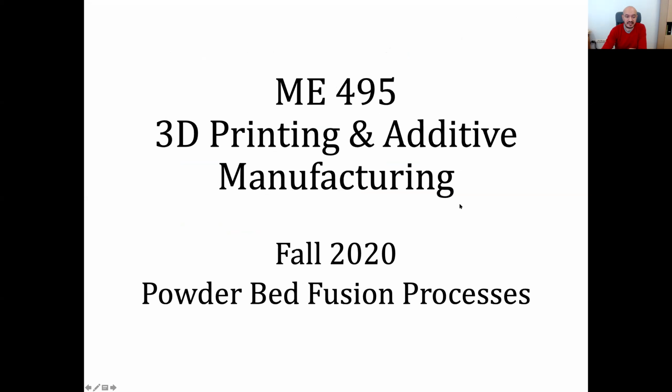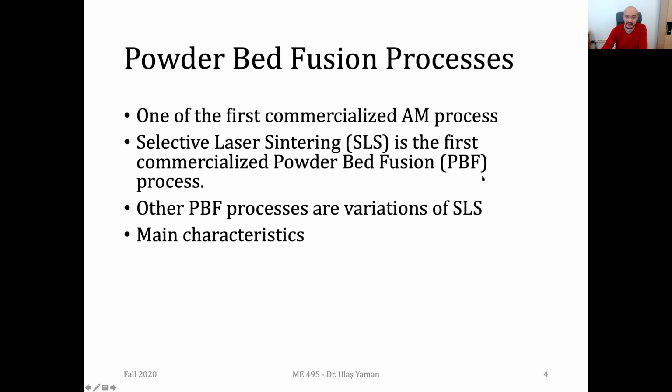At this point, we were discussing the fundamentals of powder bed fusion processes. We said that it is one of the first commercialized systems, especially selective laser sintering. And it's again an example of powder bed fusion processes. The manufacturing is performed in a closed chamber, in a powder bed. And the first commercialized type is selective laser sintering. So the powders are sintered together, not melted, but we will see that there are also some processes where they melt the powders and join them together.